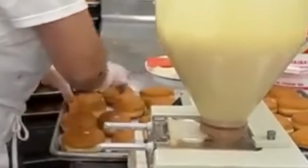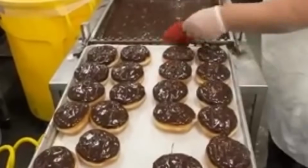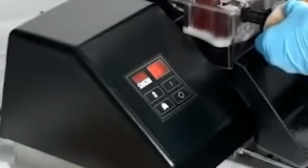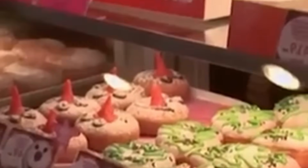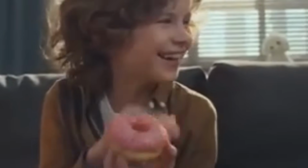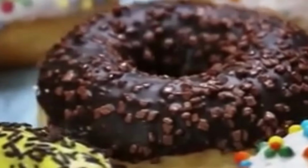Filling volume is calibrated to prevent leakage and to ensure weight compliance. Injection heads are sanitized between runs using a self-cleaning piston flush system. Production of limited-time donuts uses custom molds or dies fitted to the standard sheeting line. These are swapped in and out using quick-release clamps mounted on the cutting head. All process conditions remain unchanged except for shape and possibly finish.